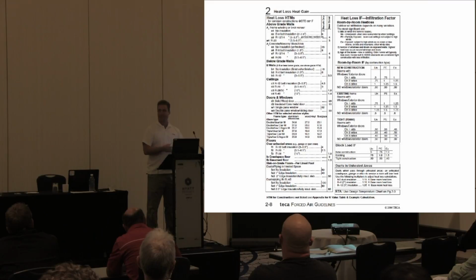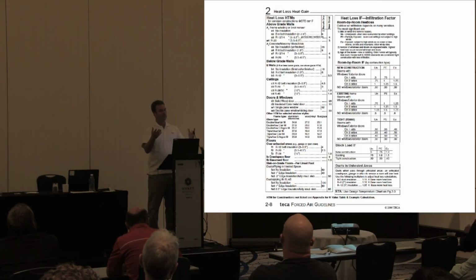Because when you have single pane windows, like, I don't know, Terry's house has single pane windows, in an old house in Victoria, and somebody phones in to put a heat pump or a gas furnace in their house, and you're going, well, I'm going to have to put a 100,000 BTU furnace in your house, but if you change your windows, we only have to put a 40,000 in. It's a big chunk if they go put new windows in their house.